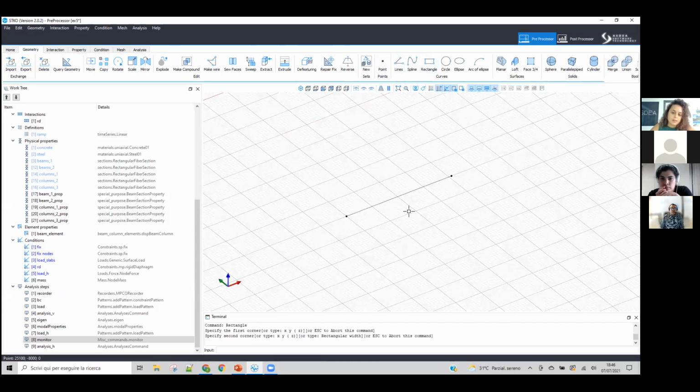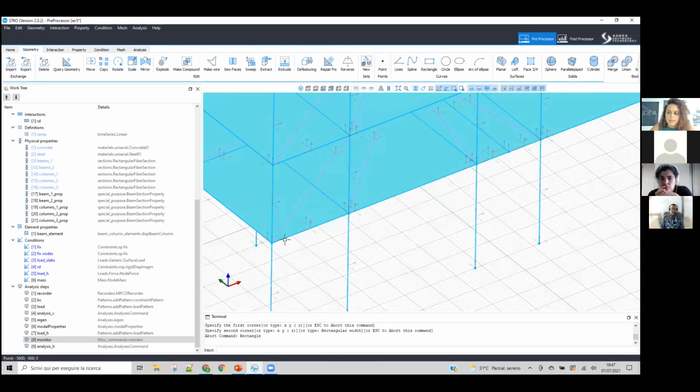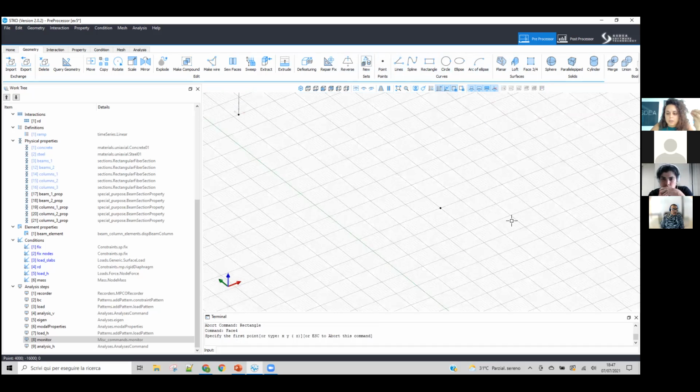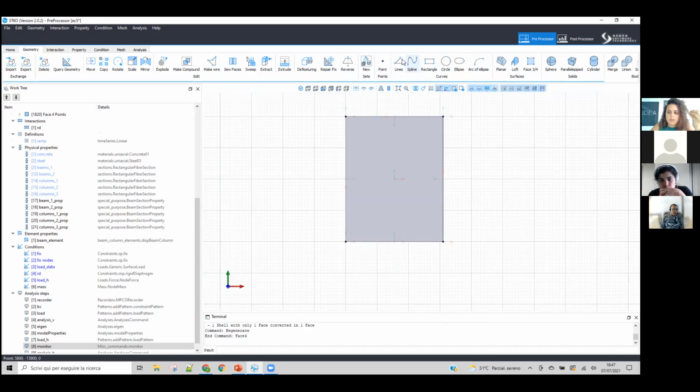You remember that at the beginning, the procedure was to create a node in the joint, then distance it from the beam nodes and move it far away, create some equalDOFs between the nodes, and then put it back in. Yes. So when you move it back in, the interaction is actually collapsed in one point. We can do this with the example that I made with the face and the line on the side. So if I put myself here, I create a line.